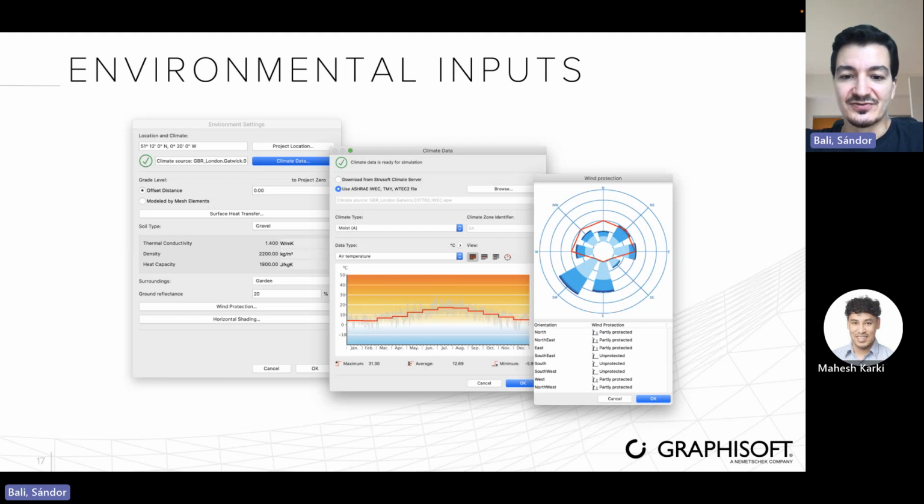So basically, Energy Plus is also an energy performance simulation tool, and the EPW format is their file format, but it's used as a standard by energy simulation tools. So it contains a lot of comprehensive weather data, including the temperature, the wind speed, the direction, solar radiation, humidity, precipitation, and all these things. Right, so this is going to define what is going to be our climate where we have our building.